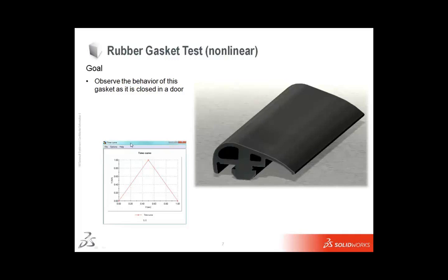And we're also going to load it and unload it. That is an advantage of having the simulation premium, is that you get to control how your loads work over time as well. Not only do you get your nonlinear materials, like rubber, you get a bunch of different nonlinear material models. We'll jump into that in a second. But you can control how your loads and restraints work over time.